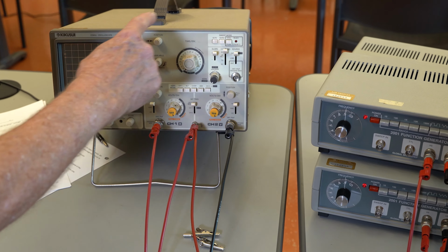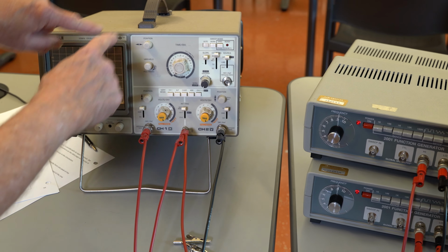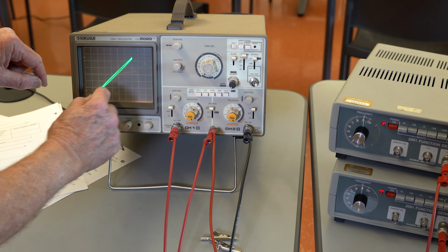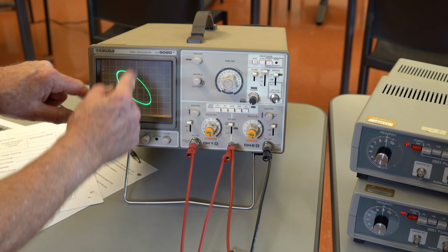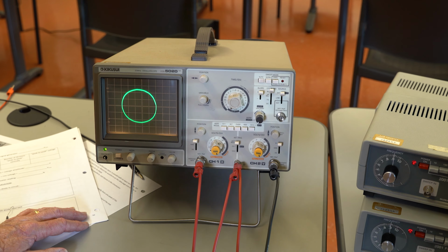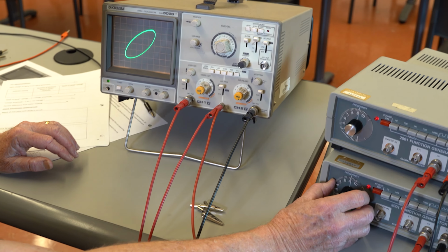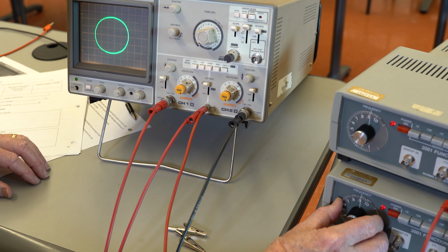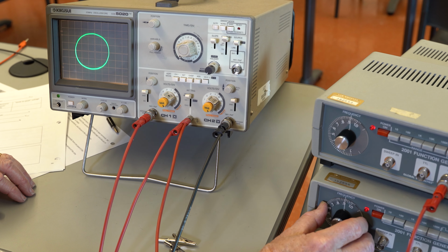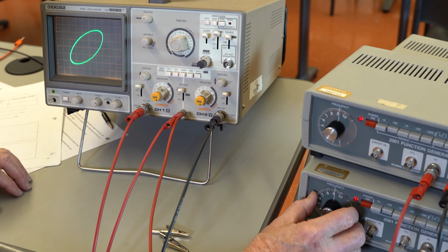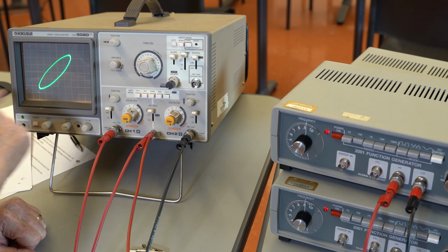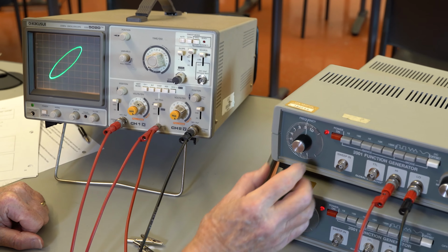When the two are in phase, it's a straight line, lower left to upper right. But if they're 90 degrees out of phase, we get the dot going left and right at a different time, it's going up and down, and so we get this circle. If I could exactly match the frequencies, it stops. So they're 90 degrees out of phase. Now, what if we made it go up and down twice every time it goes left and right once? That would be a 2 to 1 ratio.